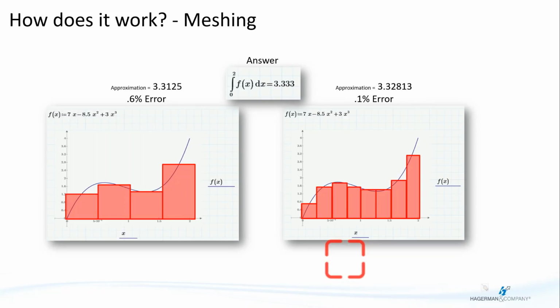What does it really mean to be accurate in an FEA model? And the time it takes to run. So in this case here, I doubled my work and I only gained 0.5 percentage point of error. So not really worth it in that case. And there comes a point in your mesh as well where it's not really worth it. But initially, you're definitely going to want to reduce that element size at least once.